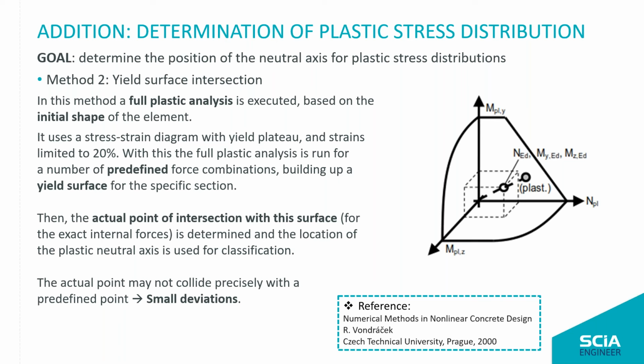The advantage of this method is that, well, it's slightly slower than the elastic one, of course, because we have to still calculate this cloud of points instead of just bursting out the formula. But we can save this cloud of points, and then for any next combination of forces you will have, you will be able to reuse the already calculated points, and it will go rather fast.